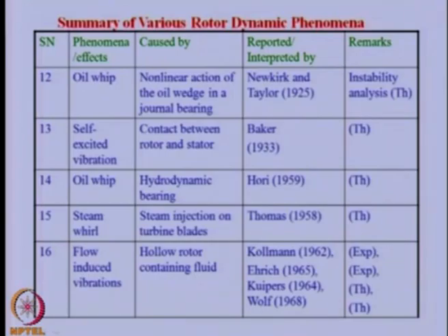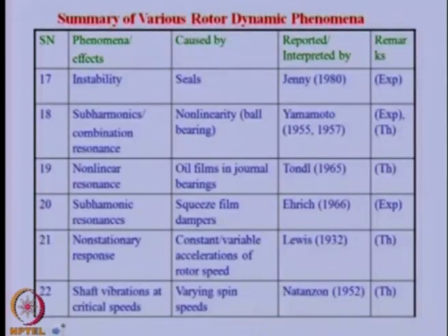Flow induced vibration in hollow rotors containing fluid was described by Coleman and others, both theoretical and experimental works. Instability due to seals was reported by Jennings in 1980. Subharmonics and combination resonances due to nonlinearity in the ball bearing were reported by Yamamoto in 1955 and 57. Nonlinear resonance due to oil film in journal bearings was described in great detail by Tondl in 1965. Subharmonic resonances due to squeeze film damper were reported by Ehrich in 1966.